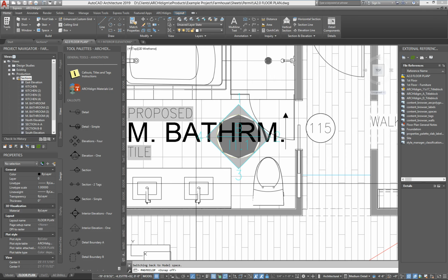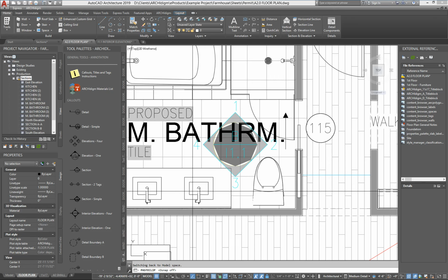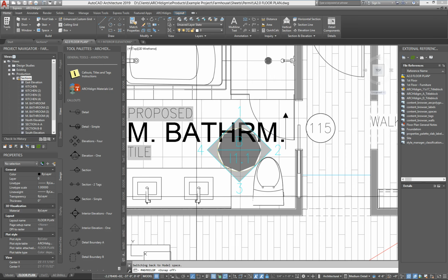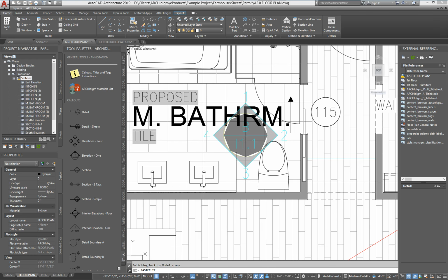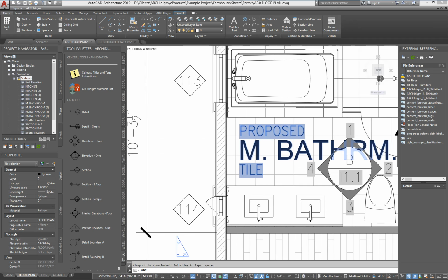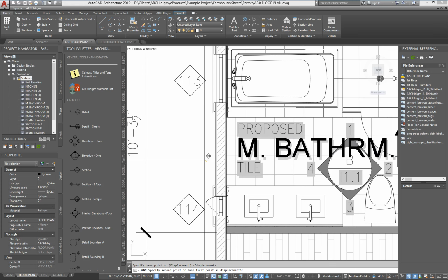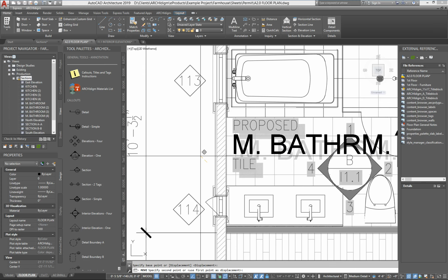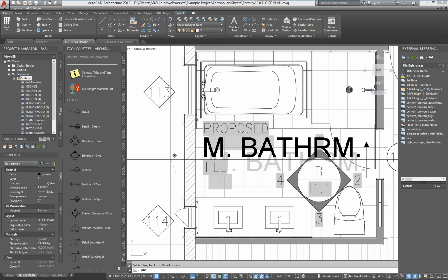And over here, I notice the placement of this symbol is in a different location because this is about the graphics of things, the presentation, where the other one was sort of a working tool version. So I think I'm going to have to place it right about here, which will force me to have to move the label. And that might be a different task. If your label is associated with your spaces, you may have to work on your spaces file to do this.